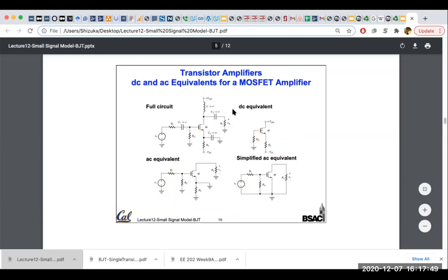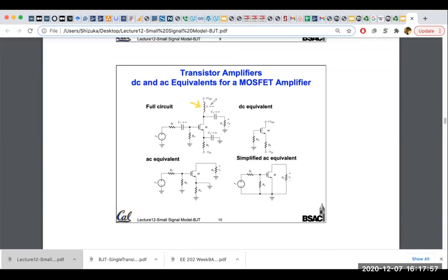So this is again doing this for a MOSFET, same logic. And as you can see here, it put a choke here. In the actual systems we usually put an inductance here. It's not a big inductance. We put a cap and we make these L and C, we make sure that they resonate, instead of putting a very high inductance. Okay.